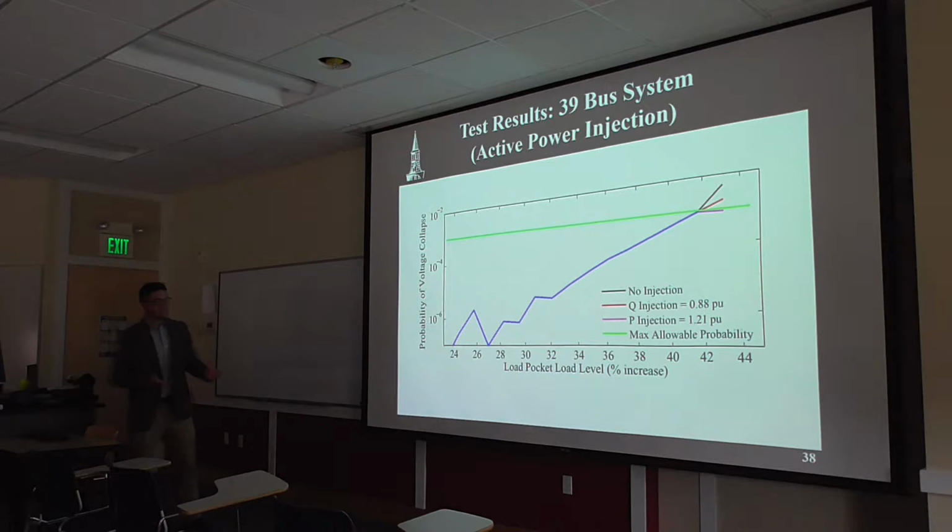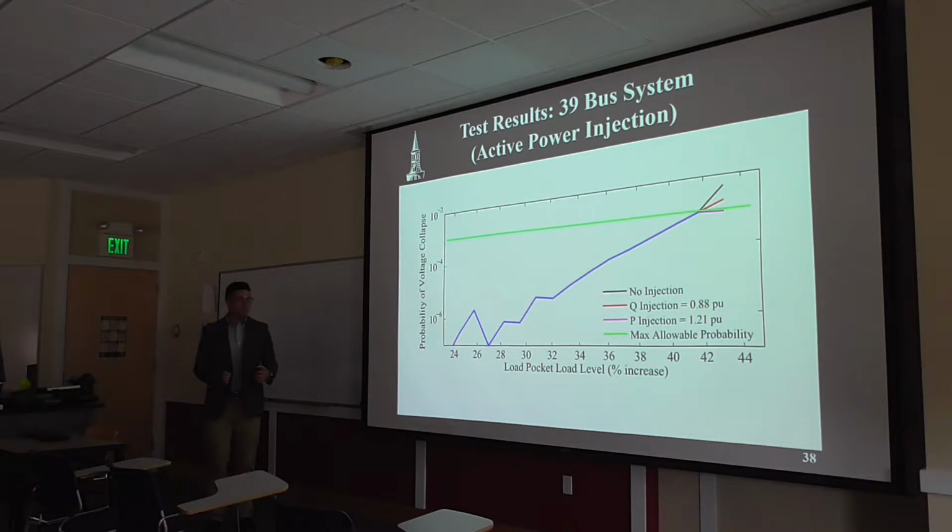So the purpose of this experiment is to show that we could potentially trigger active power resources to come online if bus voltage variance is high and bus voltage magnitude is high. Because if both of those conditions are met, reactive power injections may have diminished their usefulness.